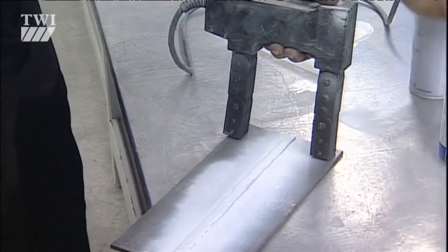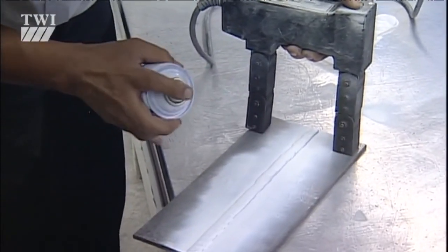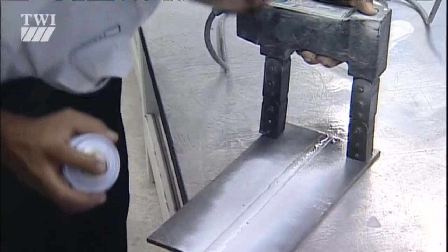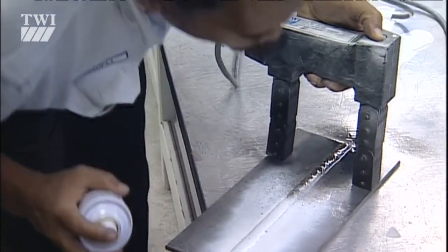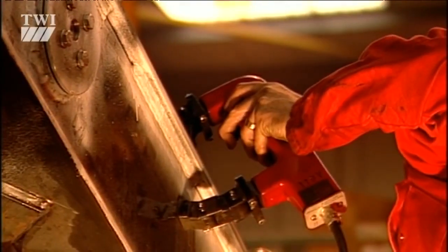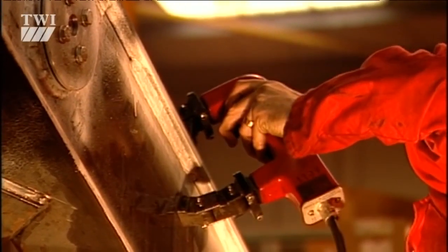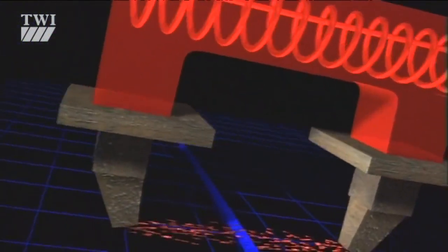Well, let's get started with magnetic particle inspection. We use MPI, as it's known, to find surface and just beneath the surface discontinuities in ferromagnetic materials. And we do it by introducing a magnetic flux into the material.